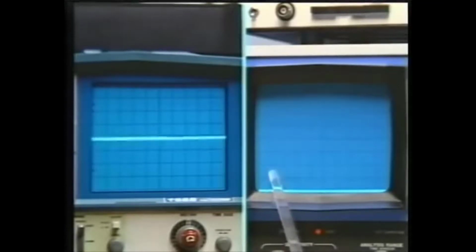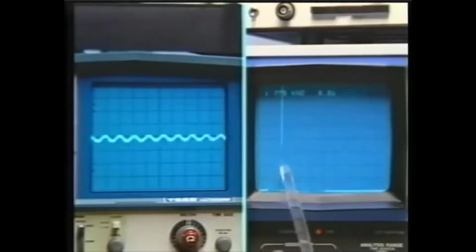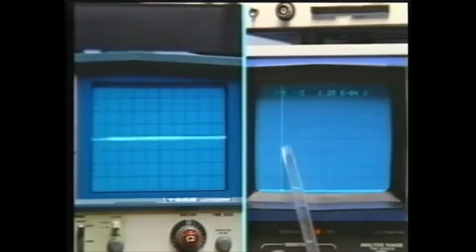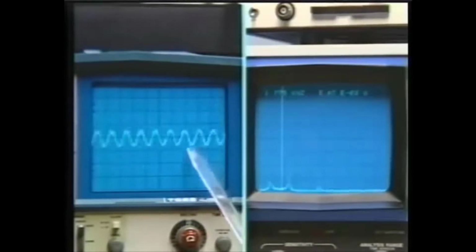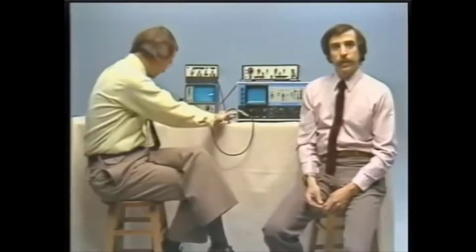Here we have the first spectral line, and we can compare that with the first spectral line that we had before, which was at 1.775 kilohertz, and once again you see that the time waveform over here has been scaled by a factor of 2. So once again we see that time and frequency scaling really works. Incidentally, as Sandy pointed out, and rightfully so, the glockenspiel really is a pretty complicated signal, as a graduate student and I found out when we were preparing the original glockenspiel demo.